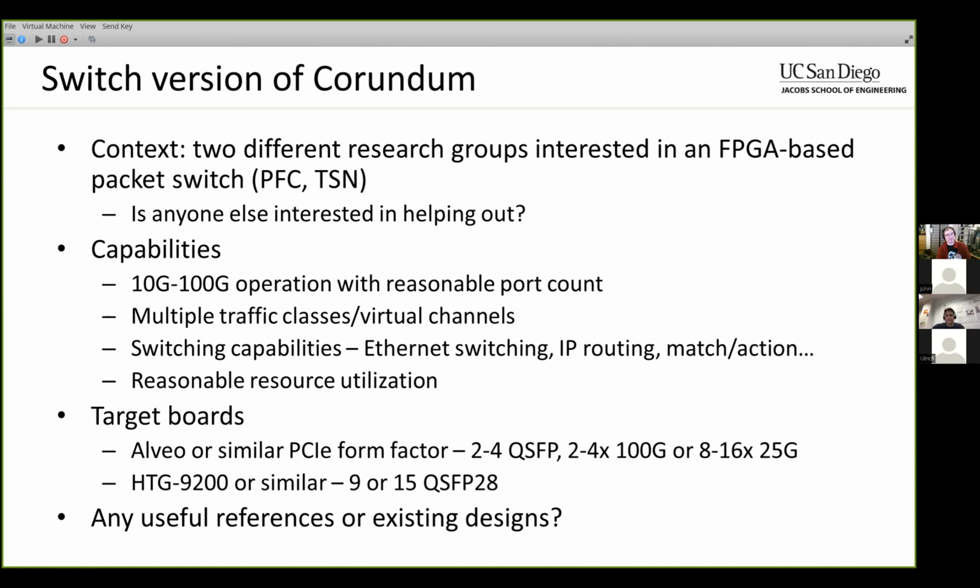I think maybe in the future, I thought about that recently. Do we actually need to transfer the whole timestamp, or can you just transfer, say, the lower 40 bits or something like that? Just a couple bits of the seconds portion and all the nanoseconds portion, and then reconstruct it, because realistically, how long are these packets going to be hanging out inside the data path? You might be able to just fetch the upper portion of it and use it, as opposed to having to schlep that around. Not sure. I'll have to take a look at that at some point.